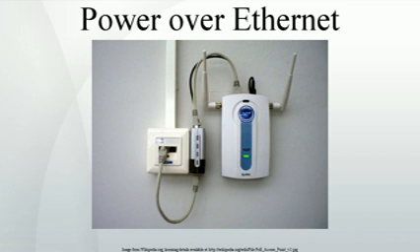A phantom power technique is used to allow the powered pairs to also carry data. This permits its use not only with 10BASE-T and 100BASE-TX, which use only 2 of the 4 pairs in the cable, but also with 1000BASE-T, gigabit Ethernet, which uses all 4 pairs for data transmission. This is possible because all versions of Ethernet over twisted pair cables specify differential data transmission over each pair with transformer coupling. The DC supply and load connections can be made to the transformer center taps at each end.